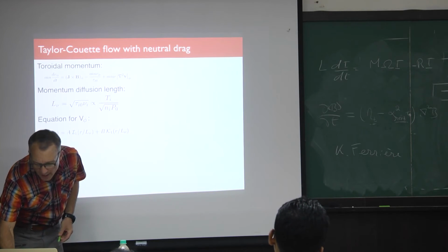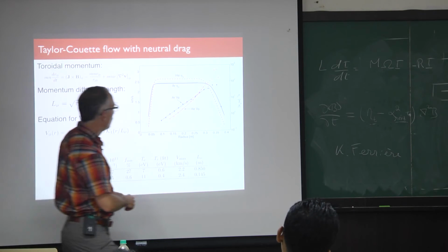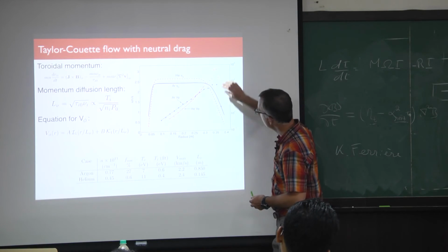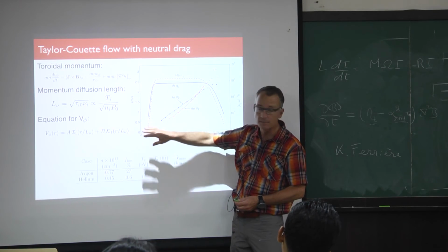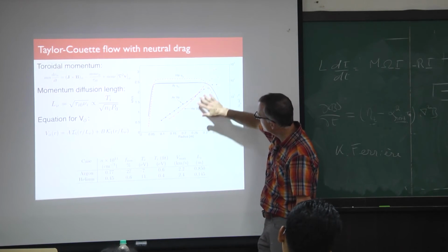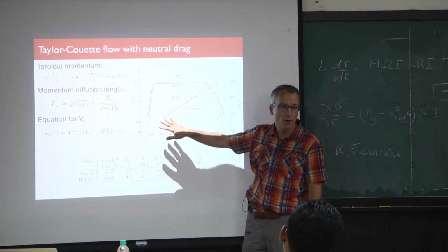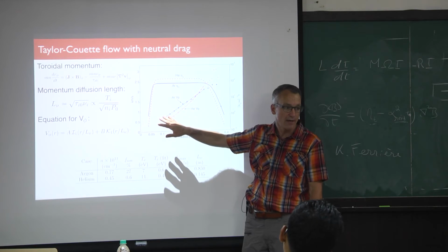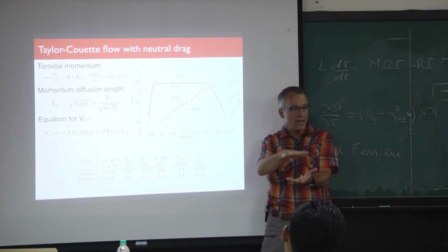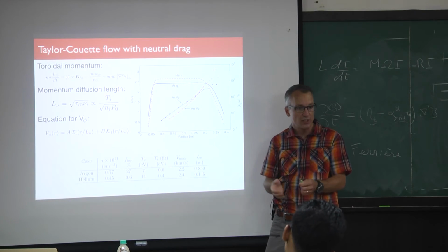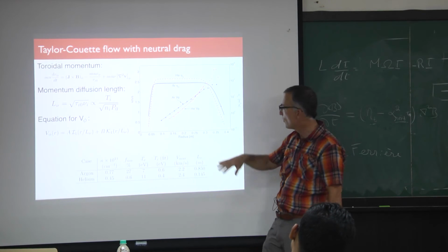So in the Couette experiment, what we found was we were able to stir from the outside, letting the inside do whatever it wants. The momentum diffuses inward, but it deviated from the straight line profile that we expected without any drag. The curvature of this line is representative of the drag term, which is acting like a body force to cause the momentum to drop more rapidly.